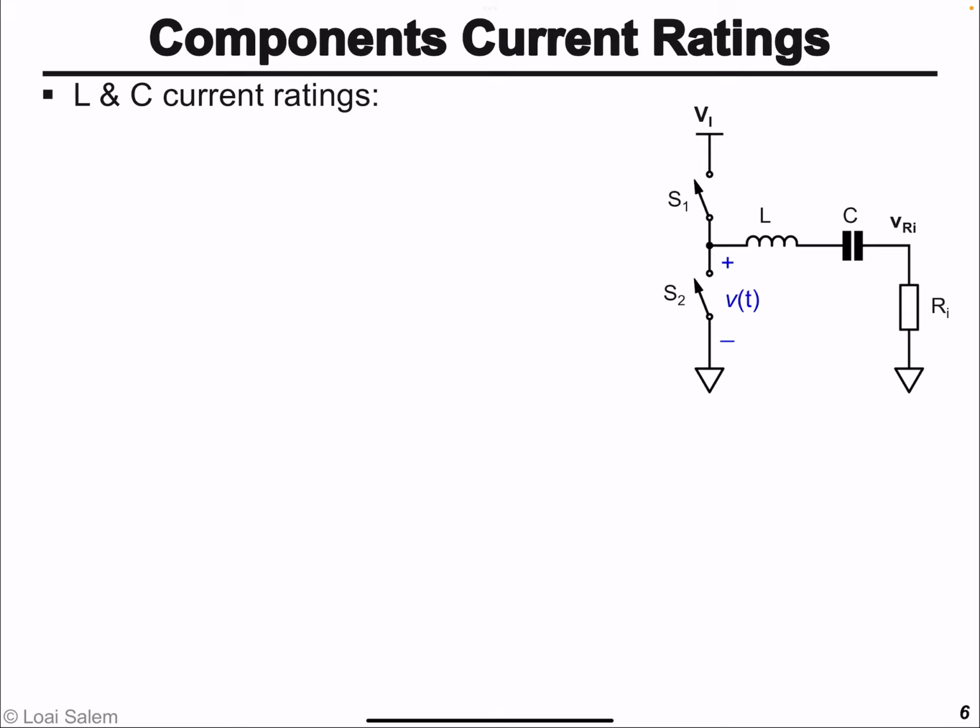And so from that we can easily find the current rating for the inductor and the capacitor, so that we can select the right components that can handle that current from a supplier, say DigiKey, Mouser, or any other electronic components supplier.